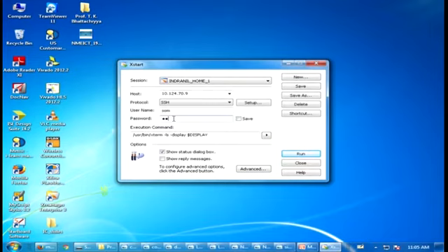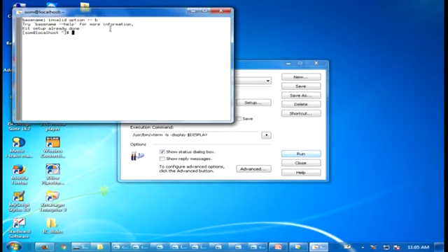It is very, very bad. If the harmonic distortion, your nonlinearity, is high, then the third and fifth harmonics will come. Your fundamentals are weakened because the energy gets distributed to those. After the mixer, you need a filter, and then you get an A to D converter. The A to D converter has to work in a linear region. So you can take a 12-bit ADC.